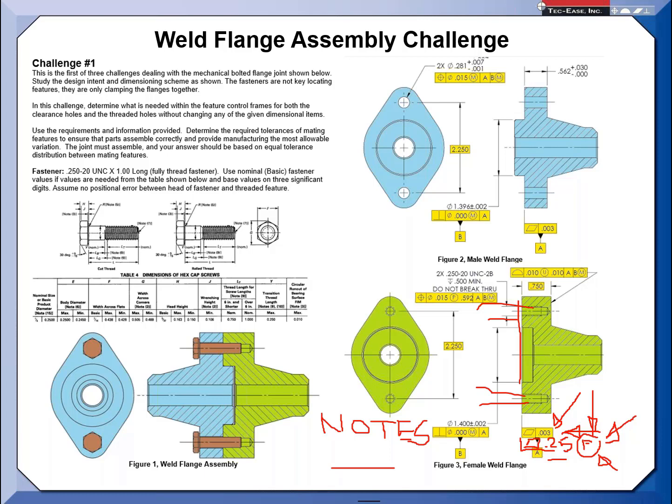material. They molded it, so in the mold, that was perfectly real good geometry. When it popped out of the mold, they twisted. So the drawing didn't have any restraint on it, so of course it failed every time. I said, well, we got to restrain the part. We're going to add a note, and we mimicked how the part restrained in the actual missile assembly and how we clamped it. We restrained the part. We had to build a fixture. Once we then measured the part in restraint, the covers passed all day long.